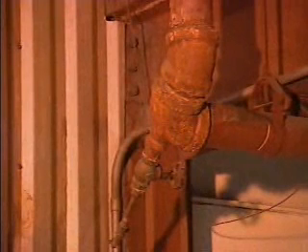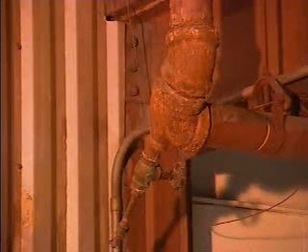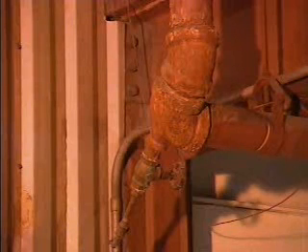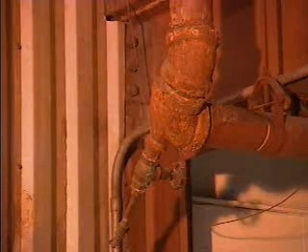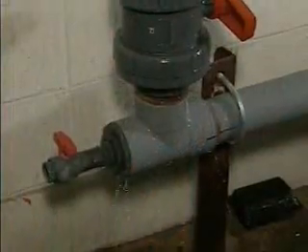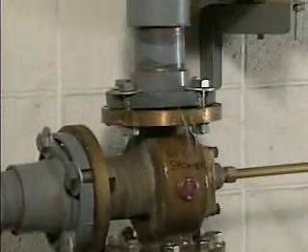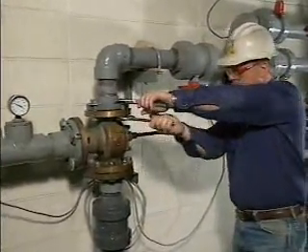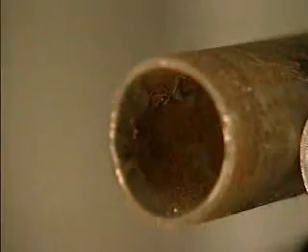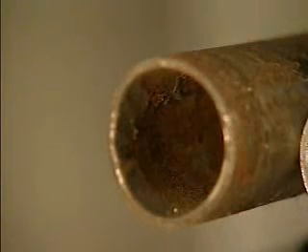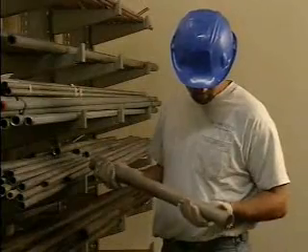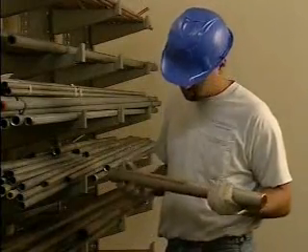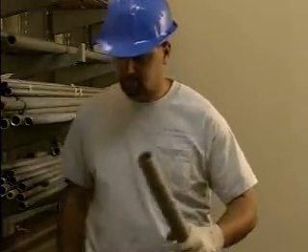External corrosion occurs when a condensation of moisture from the air or another source forms on the outside of a pipe. This makes the pipe appear to sweat. Over time, this moisture causes corrosion, which wears the metal away. Any dripping liquid can cause external corrosion as well. To stop continued external corrosion, the source of moisture causing the corrosion must be identified and eliminated. Internal corrosion results when oxygen in the air dissolves into the fluid carried by the pipe. Choosing a pipe material that doesn't interact with the environment, such as stainless steel, will help reduce both types of corrosion.